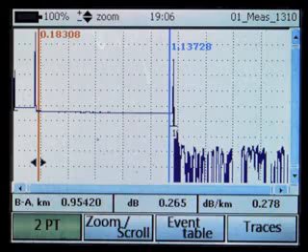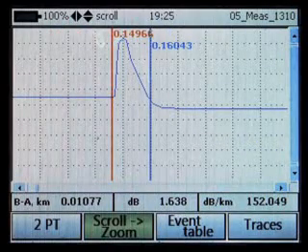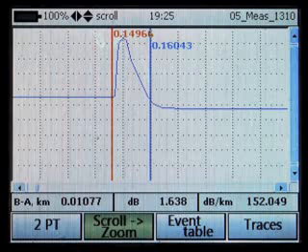How did we manage to get such a cleaner trace? Well, one thing was most important in doing that. When the OTDR chose its own parameters for an auto test, it chose a 25 nanosecond wide test pulse. That's probably not a bad idea for auto test because you don't know if the cable's 1 meter long or 20 kilometers long. But it's certainly not optimal for our 1 kilometer cable. There's a lot of excess energy in that pulse, and that's part of what causes all the ghosts we saw in the trace that the OTDR gave us at first.